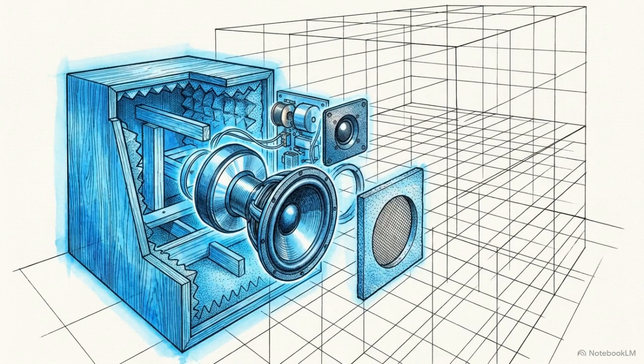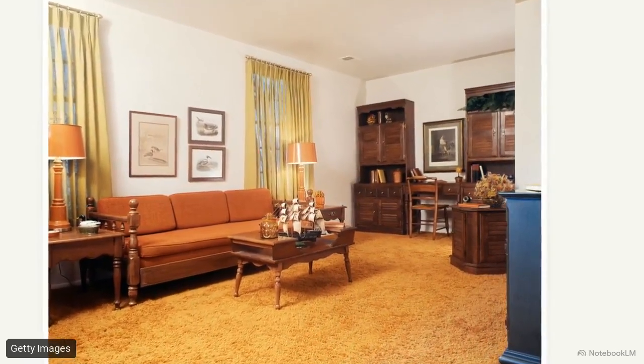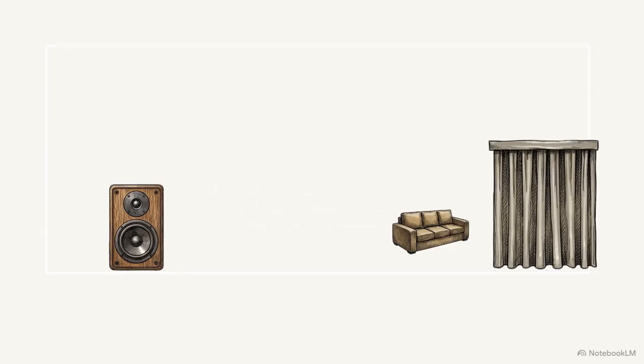The sound waves finally leave the enclosure and enter the listening room itself. Mid- and high-frequency sound waves have relatively short wavelengths. They are easily managed and absorbed by everyday architectural elements. Carpets, sofas, and curtains all pull energy out of the wave. For these frequencies, the acoustic target is a clean reverberation time of exactly half a second before the sound energy falls to 1/1,000,000th of its original value and dissipates.